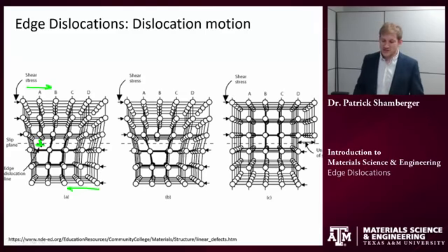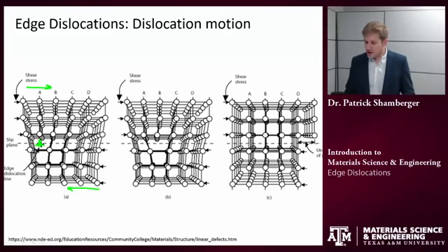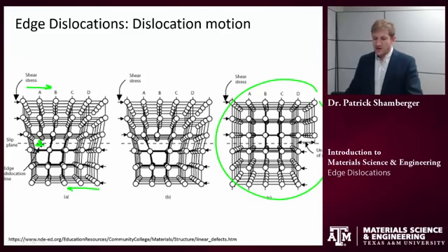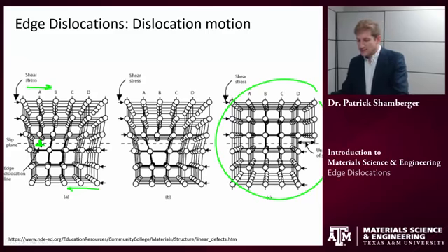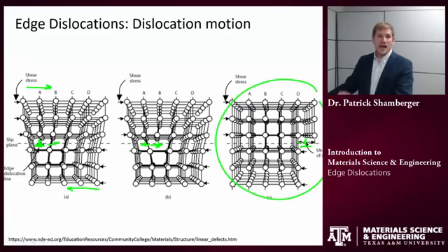And we can ask the question, what does this do to the dislocation? And the response is that the dislocation is going to move in response to that shear. You can think about this a couple different ways. One way is to think about the final point. If I'm shearing the lattice, this top half wants to move to the right relative to the bottom half. And so one way for it to do that is for this dislocation to move all the way out. And the net effect of this is for that top half of the lattice to shear one unit cell off to the right-hand side.